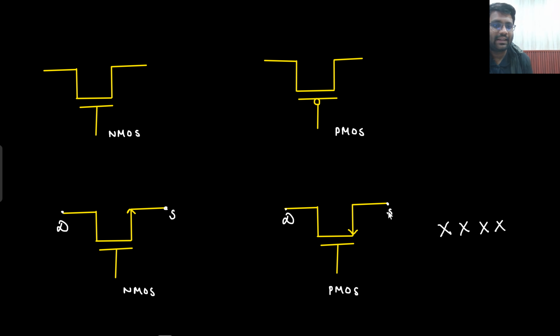This is true only for the AC analysis. Only when we do the small signal analysis is it true, but not for the large signal DC analysis. So the statement that this would be source and this would be drain is wrong.